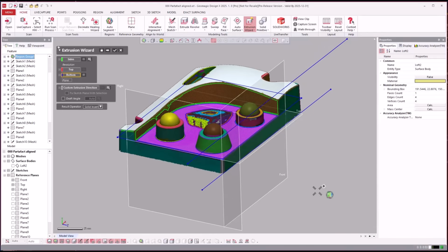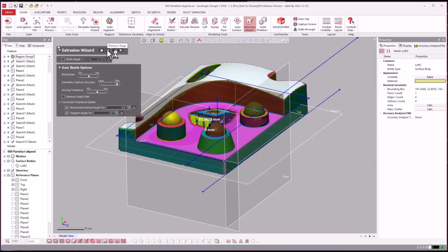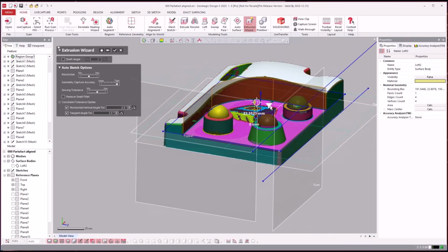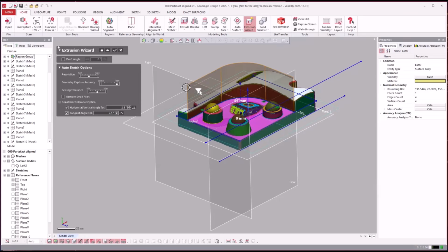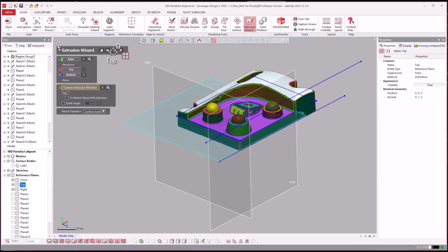So in this instance, because I didn't model the solid part, I just fit that. It's not letting me obviously do the cut. So I can just say, actually, you know what I could do? Surface insert and hit next. There we go. That's more like it. So it's just going to fit that. Now let's go back, and you can say custom direction, make sure it squares it to that plane.